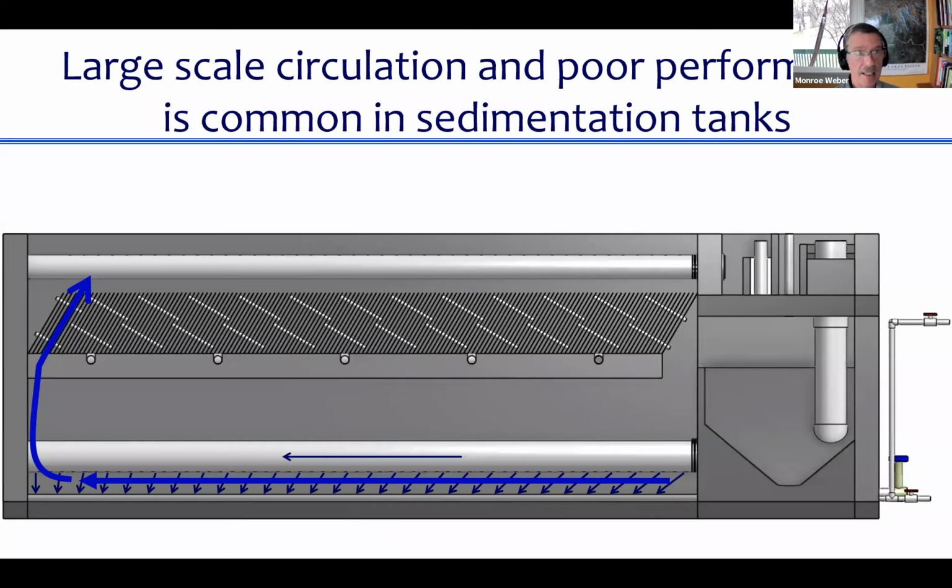And they have a large horizontal flow sedimentation tank, and it accumulates sludge over the course of 6 months. And so my former student was in there helping to clean out that sedimentation tank, and he showed me some photos, and he showed me that in that sedimentation tank, the outlet used to be right at the end of this horizontal tank.